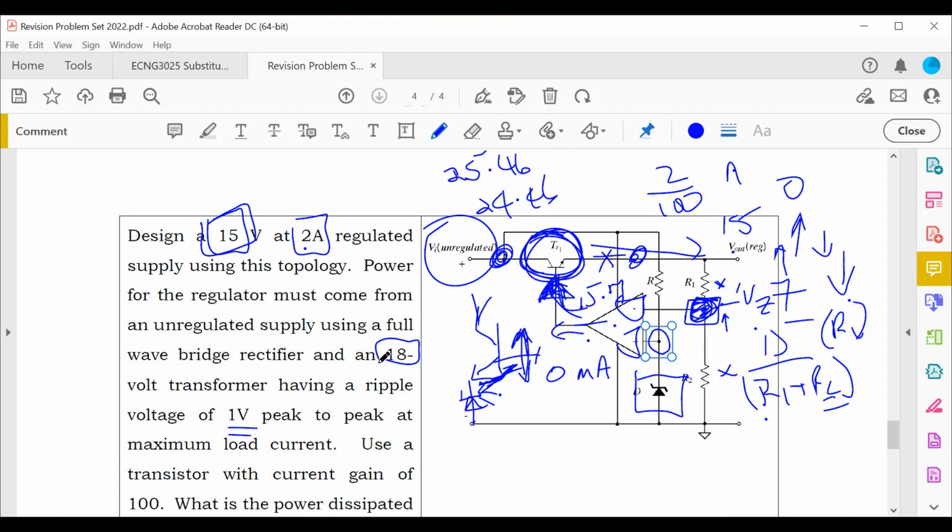And to trickle charge it, normally you need about 2 amps. So you need about 14.5 volts on the output. On the input, you could get an 18-volt transformer that could give you at least 2 amps, and you make your supply. And you have something. Yeah, that's sounding good.